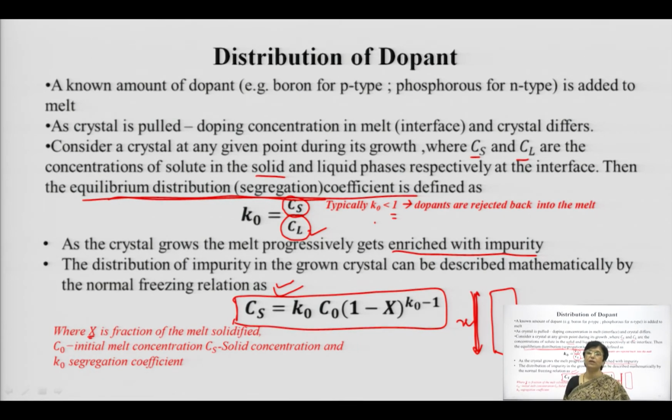So, growth is happening because the solidification of silicon on the seed crystal increases the crystal, and therefore we call it growth. This is how the similar orientation of the seed is happening, and this particular equation gives you the idea up to which you need to continue the crystal growth process, because when the impurity increases you need to stop, because that silicon ingot is of no use.